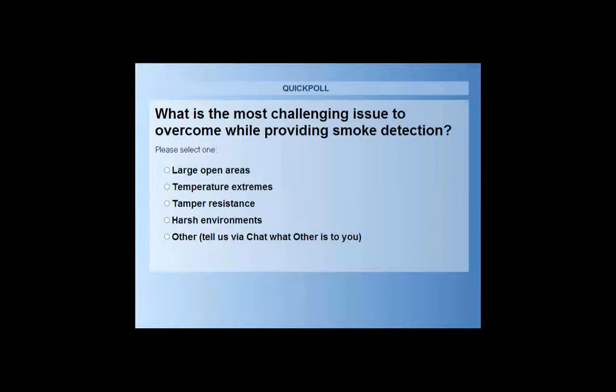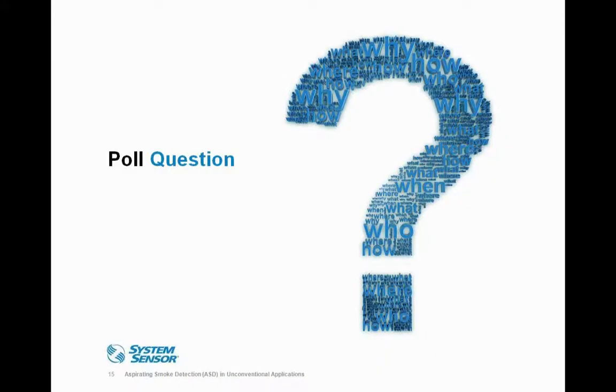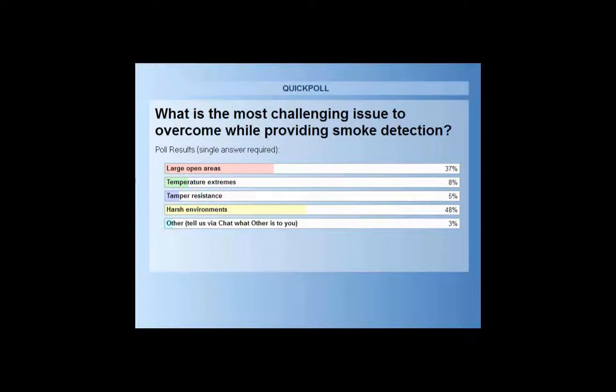So if the sample ports, let's say in this environment, are starting to clog, the product will let you know of that. And then the simple cleaning, which is called out in our installation manual, is disconnecting of the tube and the network up to the detector, and then blowing compressed air back through the pipe network to clean out all the ports. So it's compressed air, or vacuuming of the ports.